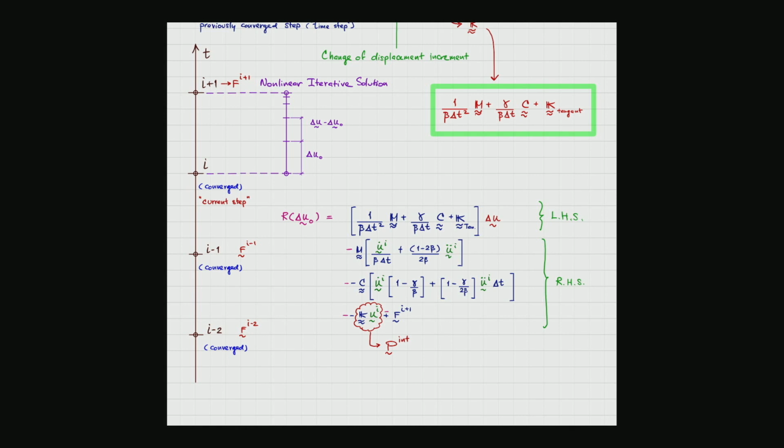Because of the nature of finite elements, as you know, if the domain is discretized, then the displacement within the domain is going to be approximated or interpolated, and the interpolation functions that we have are not capable of picking up the point or the localized information about the nonlinearities.